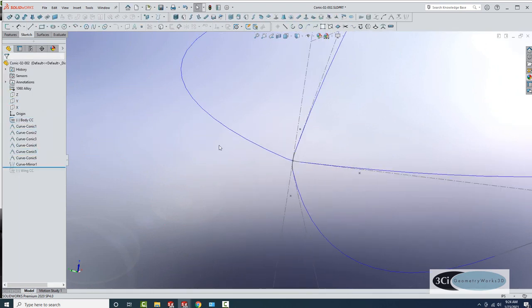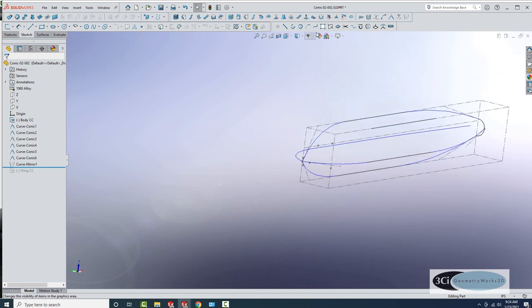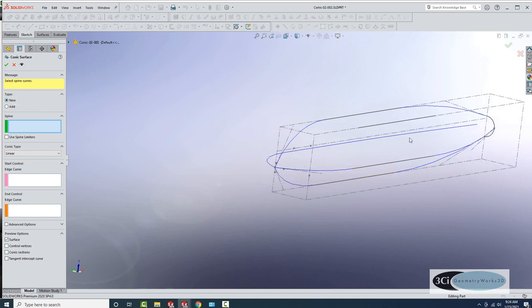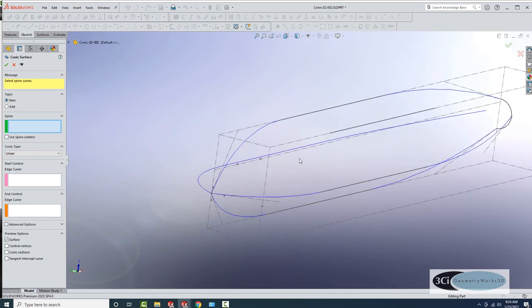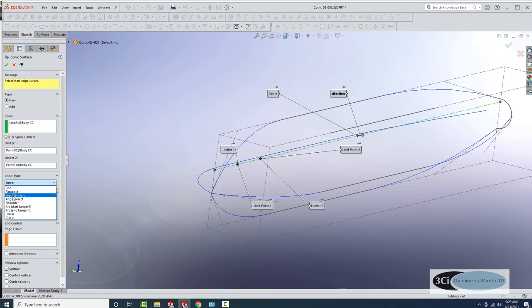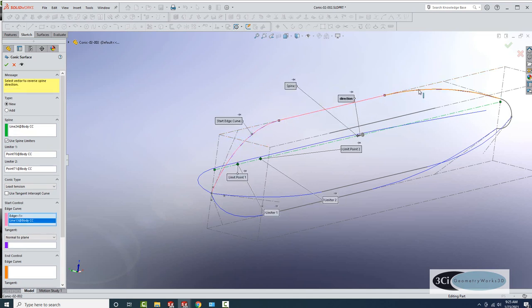So we'll start with a spine and the base conic surface. We'll establish the first conic, which has a spine, and all of the following conics will use the same spine. I'll add some limiting points. It's always a good idea to use a small sliver of the whole surface to establish your cross sections. So the limit points provide us that capability.